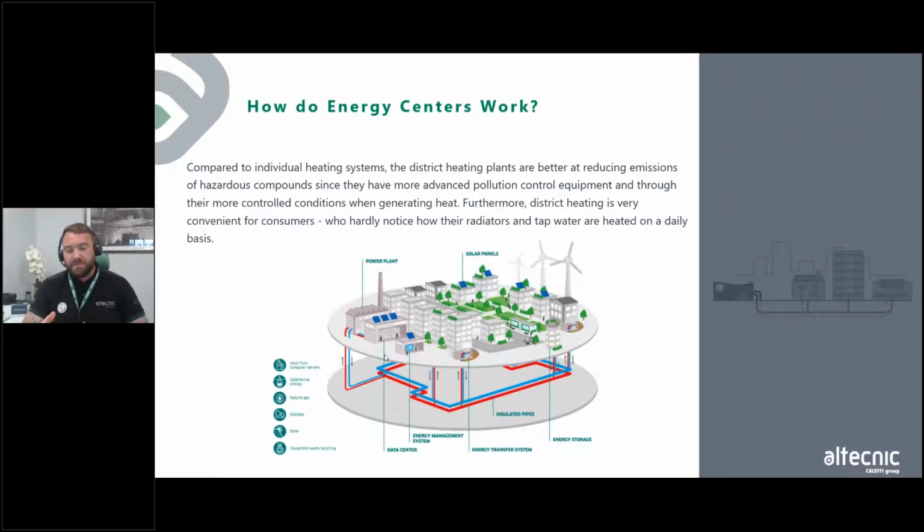Now, systems, when they're undersized or oversized, can generate problems in different ways. Generally, if they're undersized and we haven't got enough energy, that will have a knock-on effect on the end user, on the HIU, because we won't be generating enough energy. Again, if they're oversized and we've got too much energy going through, that can have a problem on the internal components of the HIU, and again have an impact on the end user.